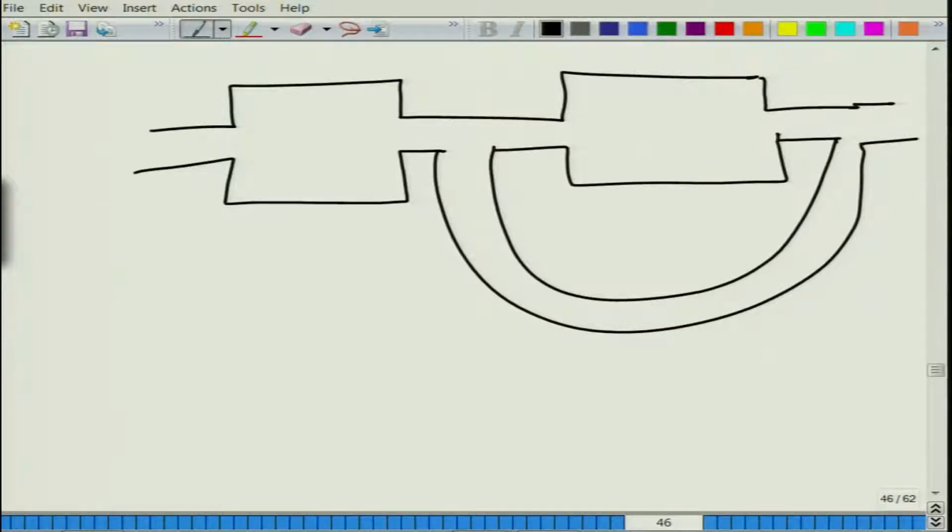Okay. So, what happens now, the acoustic waves have more than one choice of propagating. At the moment they come to this junction, they can either propagate downstream here or they can go here, and then when the waves come here, they again have a choice of constructive interference and destructive interference. So, this can be your muffler proper or muffler 1, muffler 2, and what we are doing here is providing an additional path through which the waves can go.